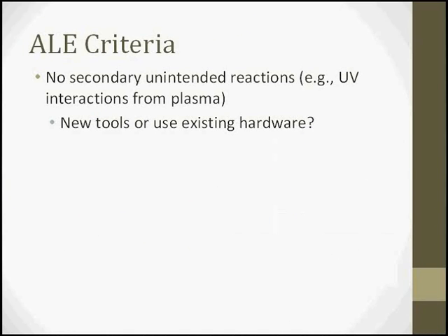So some of the ways that we may look to do the cycling would be to introduce, rather than receiving the radicals and the ions from the same plasma source, a downstream plasma to generate the radicals and have them enter the chamber separately. Or also, we may see the use of neutral beam etching coming into play.